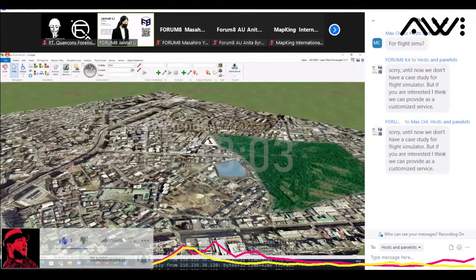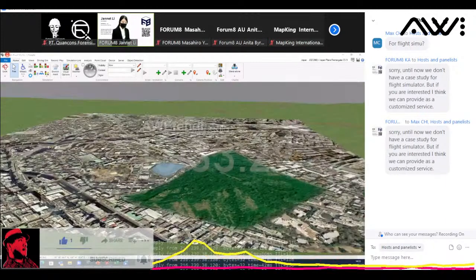The first thing we're going to do is 3.2.4 on page 19 of the guidebook. We're going to load a terrain patch. Go into edit, and there's the patch option button here. Then, of course, we load data again from the data we have saved for the seminar, go into terrain patch, and click on the XML file here.